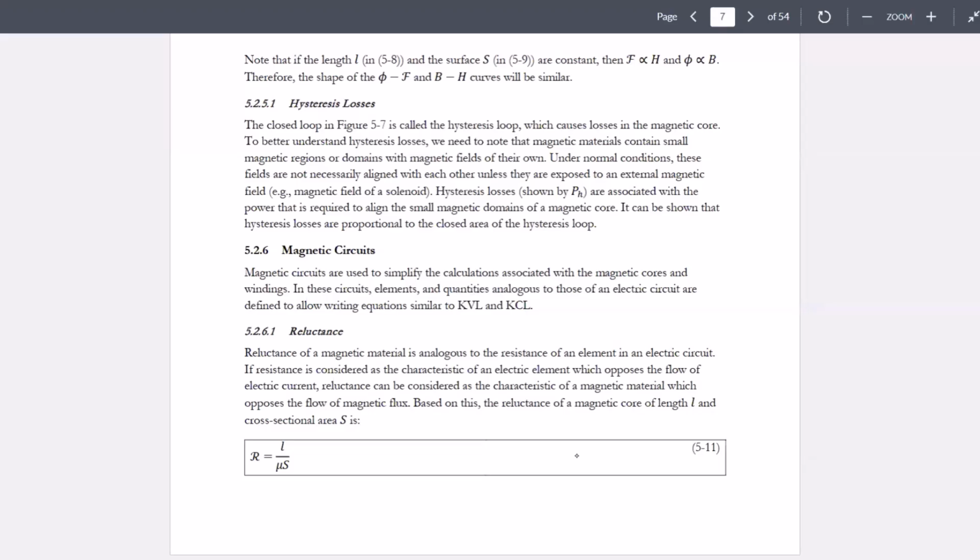Creating a motion would be when we have a motor, so a combination of magnetic fields and wires that would induce a torque on a certain object, which becomes the motor action. Or you have the same interaction between the magnetic materials and wires so that you induce some voltage in a certain winding. That becomes the origination of power generation or voltage induction, which would later on become a voltage source or a generator for you. So both of these would require a magnetic circuit.